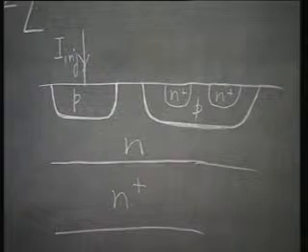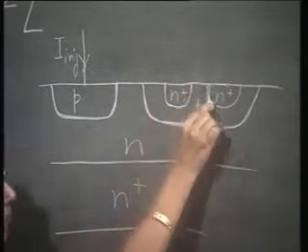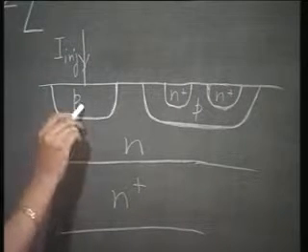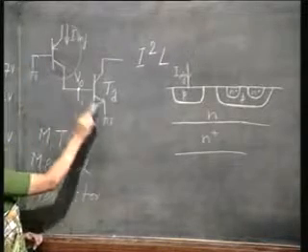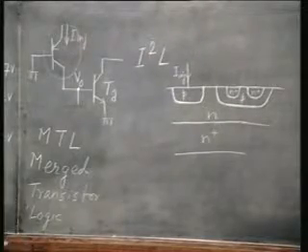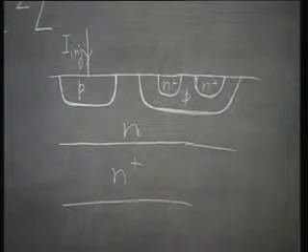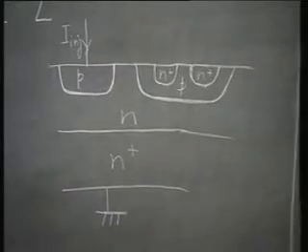Okay. In the other p region, I have diffused multiple n plus regions. I have shown only two here, it could be multiple regions. So, now what is it? Let us see, this is a PNP transistor. And you see this PNP transistor's base is shared with the emitter of the NPN transistor. So, this must be the emitter of the NPN transistor, which should be permanently grounded.